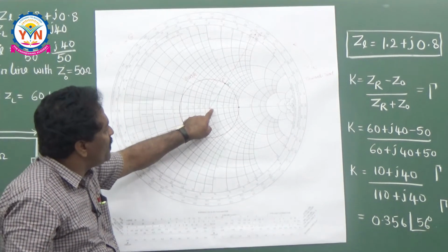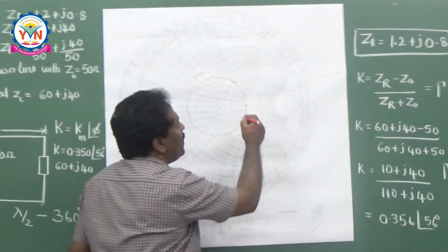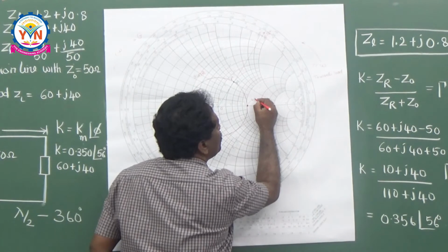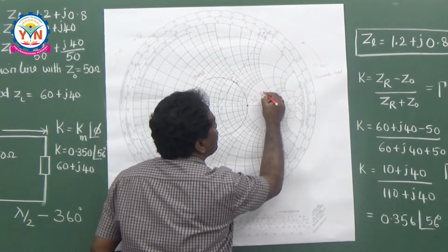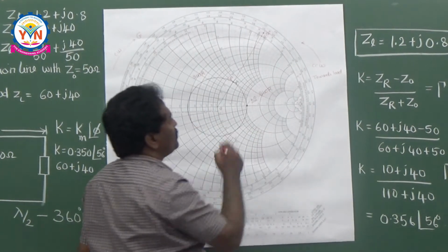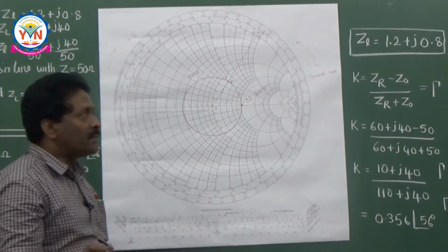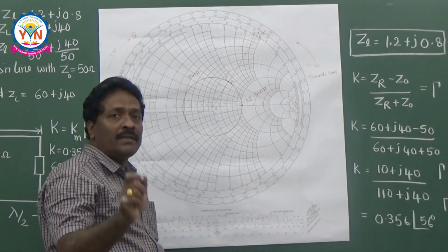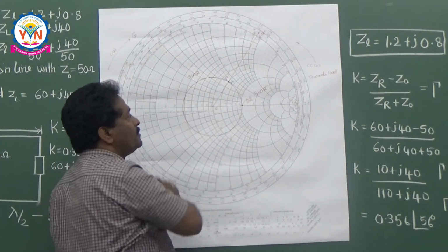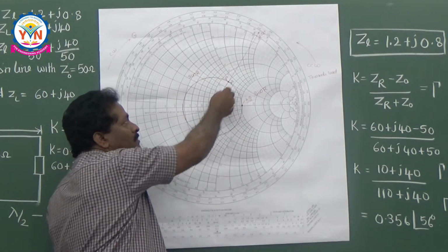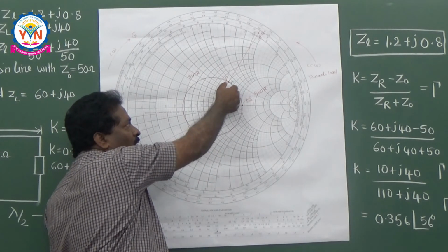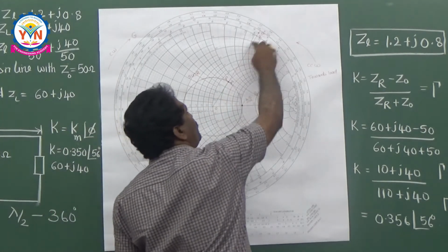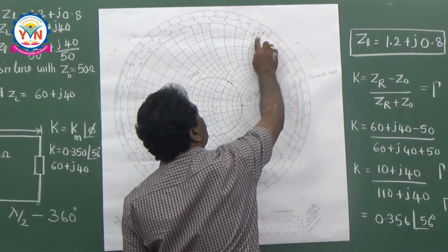So you have to identify the point of intersection here. This point of intersection is around 2. So this will be 2.0, which is nothing but your SWR, standing wave ratio. So very simple. First, identify the normalized point. Plot the normalized impedance on the chart. And then just draw the line from the center of the chart, that is called OP. Extend this OP to the periphery of the chart, then it will be Q.